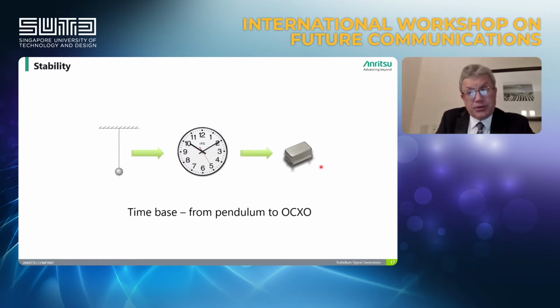If temperature changes, the dimensions slightly change, and we see some frequency instability. Furthermore, with time, the crystal material simply evaporates, the resonator becomes smaller and the frequency changes.